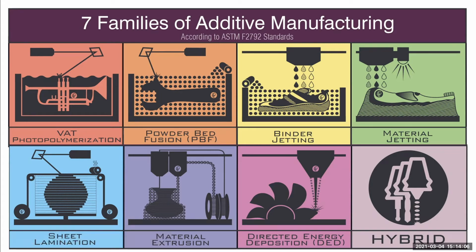And that's similar to the binder jetting and the material jetting, in which not only is there a substance being extruded from the print head or expelled from the print head, but it's also being fused directly onto the thing that it is making. So with the material jetting and the binder jetting, you sort of have this substrate that exists in open air, and then there is some form of binder that is added to it. So in the material jetting, the binder is part of the chemical process that's being injected, and then it is cured using some form of, normally UV sensitive process.